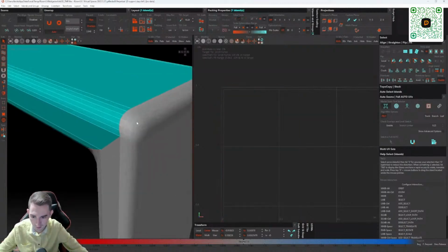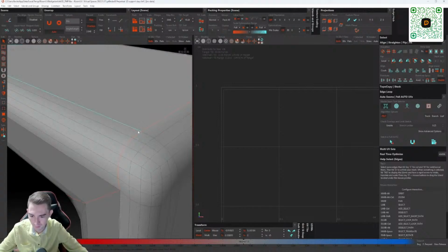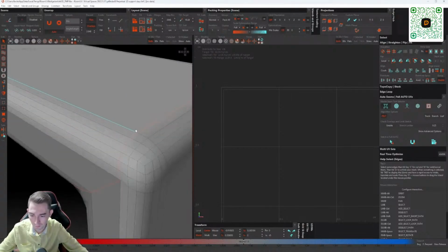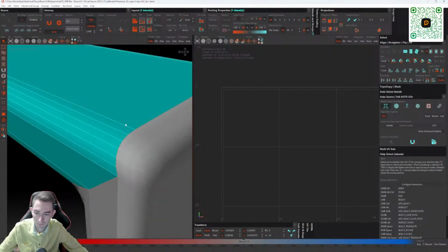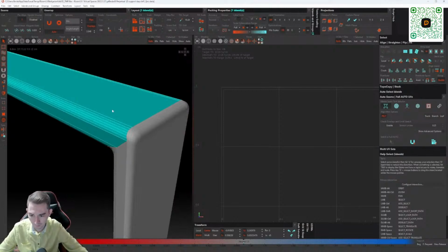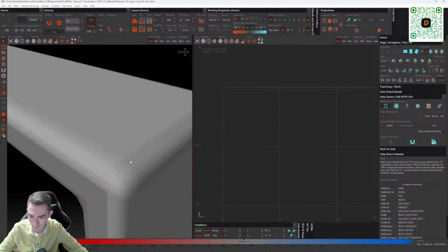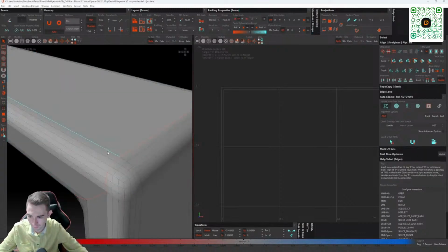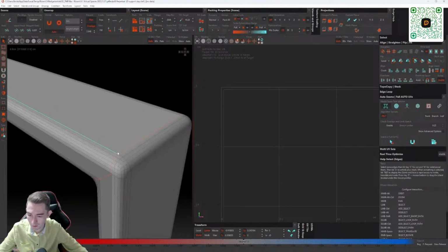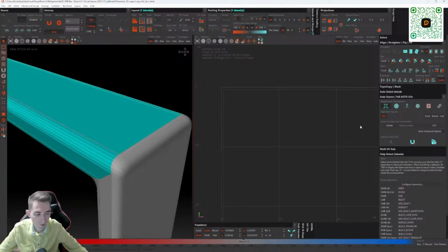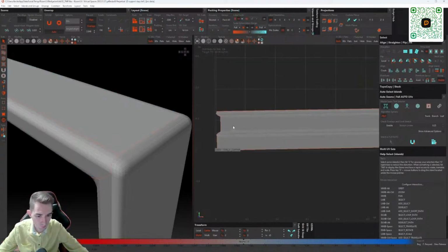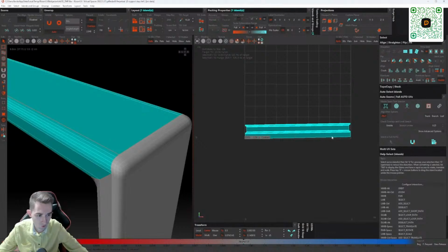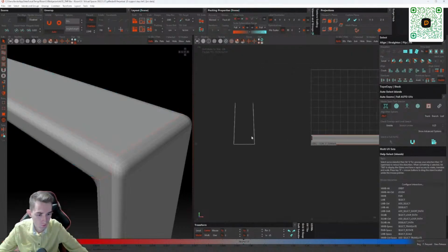Well, I don't know, it seems to me it can be divided here again. That is, with a double click select with the magnifying glass, press the C key. Select the element again, here, but no, I didn't cut it here, press F2, press C again on the keyboard. Divide, select the element, and try to unwrap it again. Yes, it's better now. In other words, there are no distortions visible now.